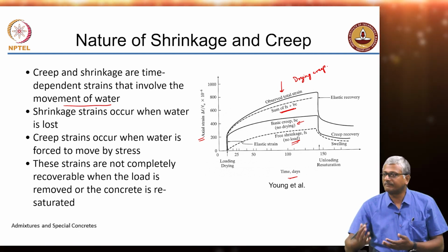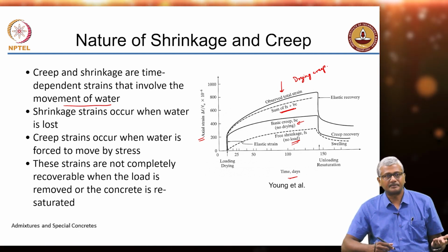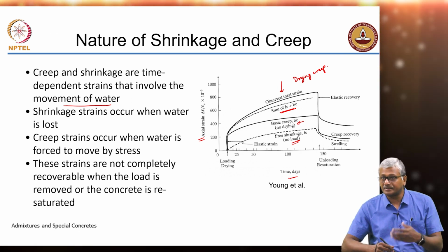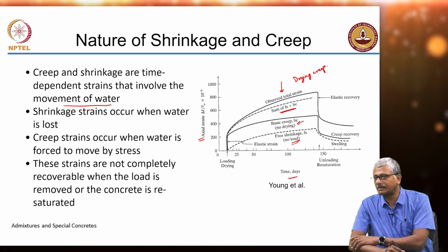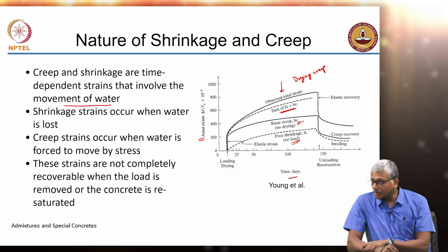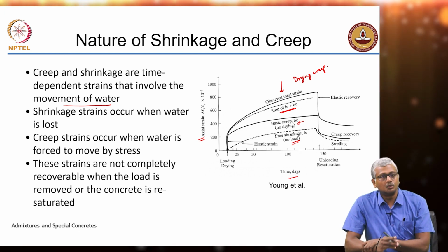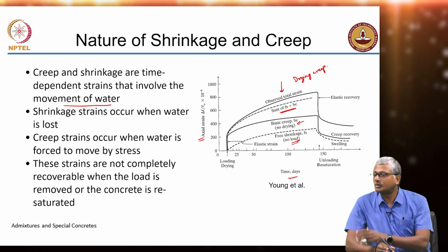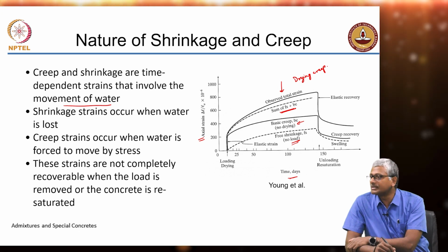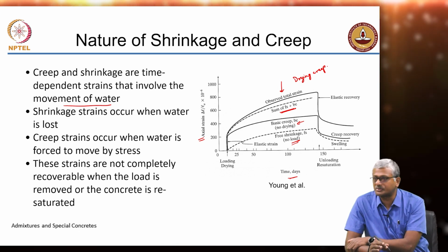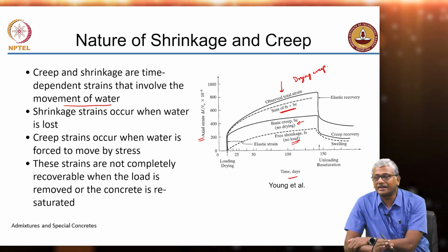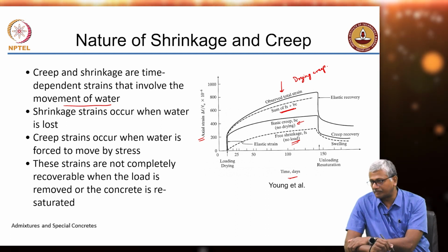So, you have both the effects of drying and the creep, and this is going to lead to a sum total of the strain that is greater than the shrinkage and the drying creep basic creep that is determined separately. So, because of this, when you do determination of creep, and today the tall building code that is out for the last 3-4 years actually tells you that when your strength of the concrete exceeds 60 or 70 megapascal, ensure that you have done the right tests to determine the effect of the creep.